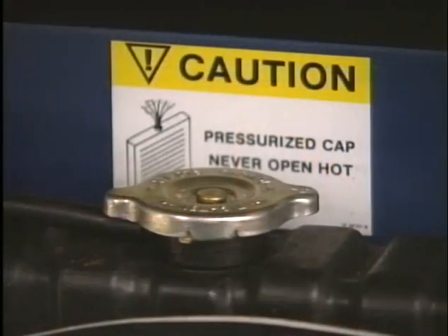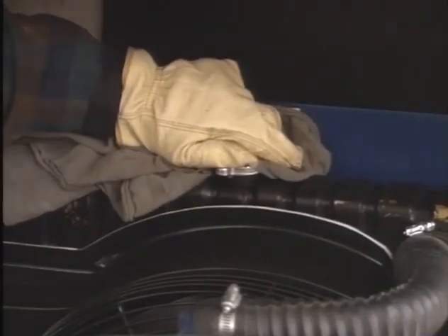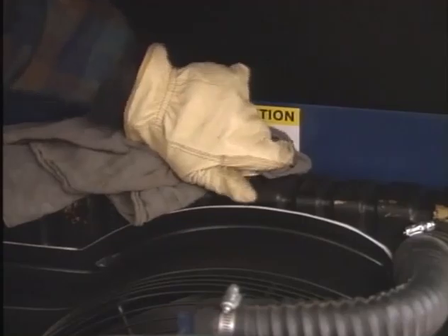Cooling system. Maintain the cooling system according to the manufacturer's instructions. Hot coolant can spray out and you can be burned if you improperly maintain or service the cooling system. Remove the filler cap only when cool enough to touch with the bare hand.